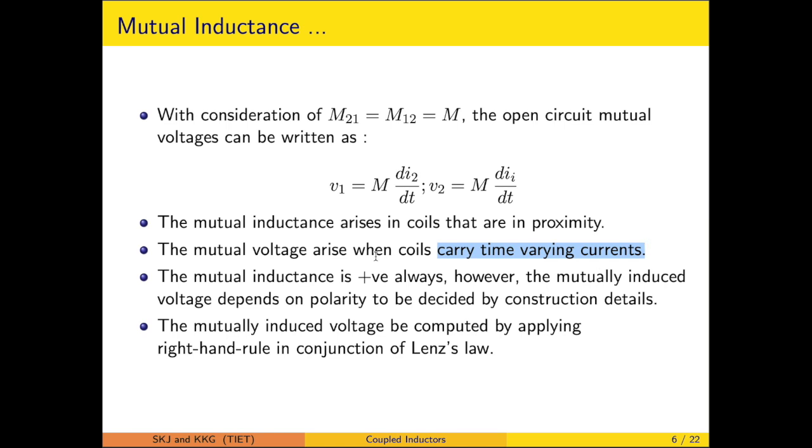Now one point which we have to note is that the mutual inductance is always positive. However, we will be seeing that the mutually induced voltage depends on the polarity, or is decided by the constructional details. The mutually induced voltage can be computed by applying the right hand rule in conjunction with Lenz's law. That is also a fundamental aspect.